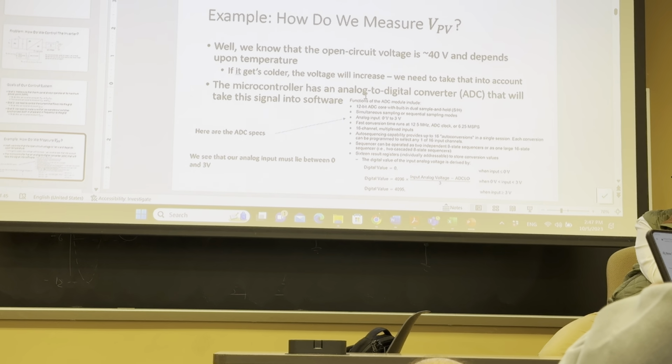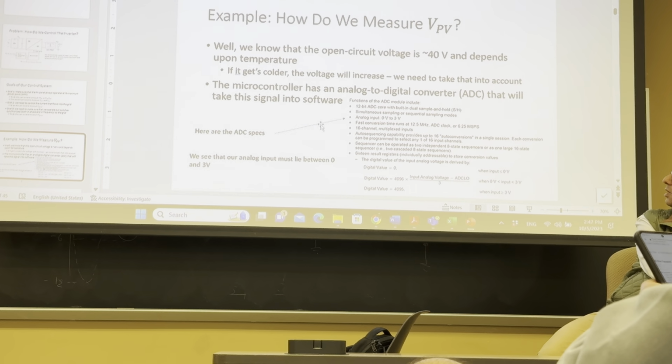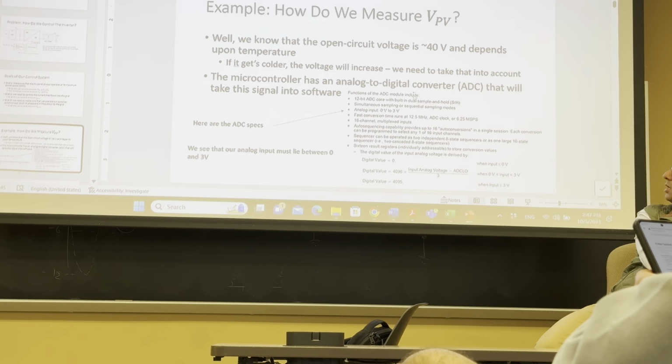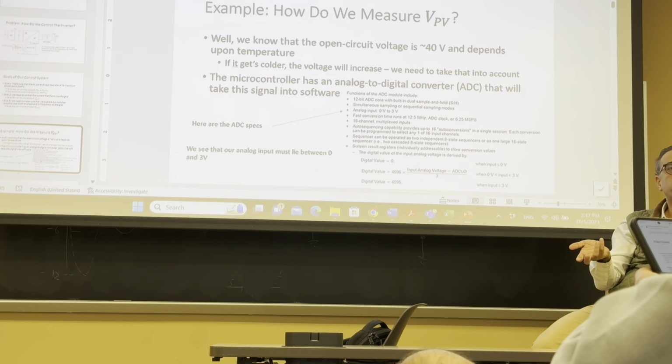Now, based on either the company experience or what we have in this case, our microcontroller kit has an ADC built in, so you can read through it. For instance, this particular one has a 12-bit ADC. The input is 0 to 3 volts, and these are things that we will talk about later when we talk about ADC sampling. But as you can see, if you want to use the analog interface of the microcontroller, you cannot just apply any voltage.